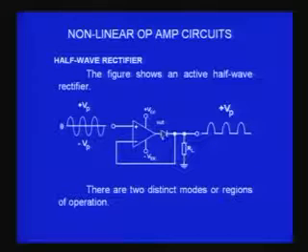When the diode becomes forward biased, there is a closed loop here, and as long as the input is going positive, the output also is going positive. It is multiplied by 10 power 5, and therefore it will be a very large voltage, much larger than 0.7 volts, and so the diode will be forward biased, and I will get the same voltage as the input is changing.